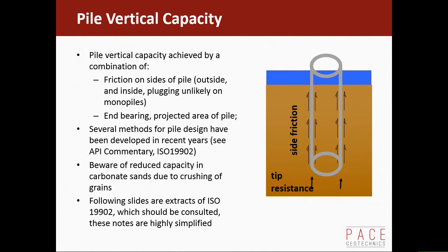So then a few years later, a few miles away, they put the Goodwin platform, and they knew there were some limestone bands there. So they started hammering, and yes, they got it about right. They didn't hammer it too hard, so the pile didn't disappear into the seabed. But they reduced the wall thickness so much that when the pile hit the limestone bands, it deformed. And so they had another problem. Because of the acidic nature. It's just the strength of it.